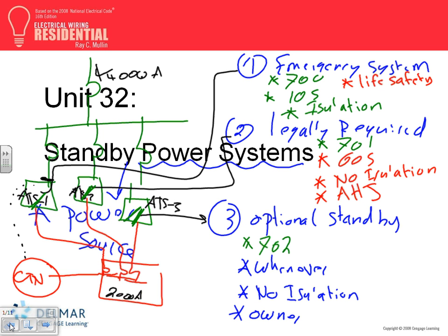Now, everything here is hot. Two problems. Number one is, if you energize the whole panel, then everything in the panel will be taking power from this outlet. This outlet is what? 20 amps. Now your dryer is going to be taking power from it. If it's a house, of course, you have a dryer, you have a range, you have everything. It's taking all the power through 20 amps. You're going to burn it, number one. Your generator will shut down immediately because it doesn't have enough juice to feed this.